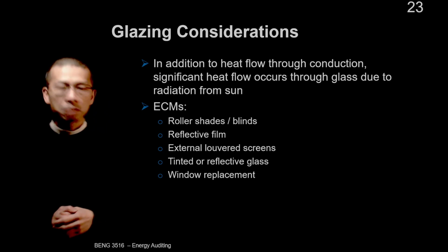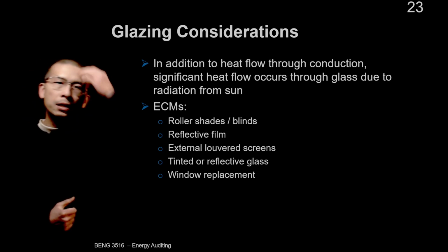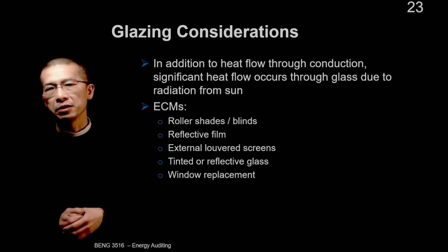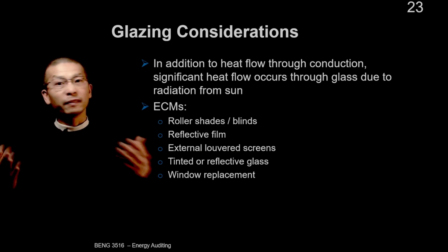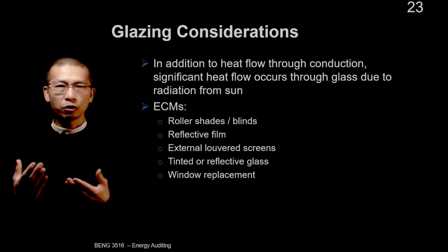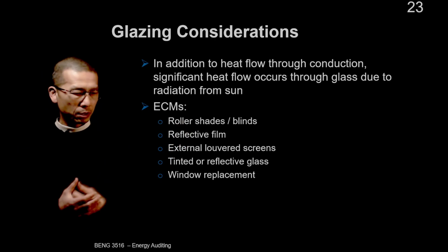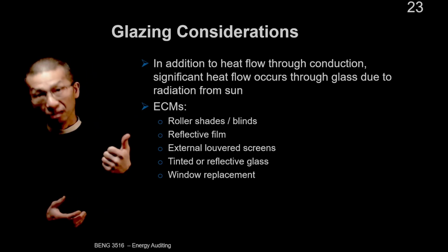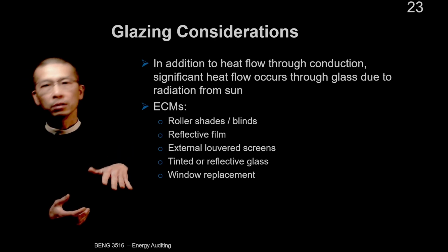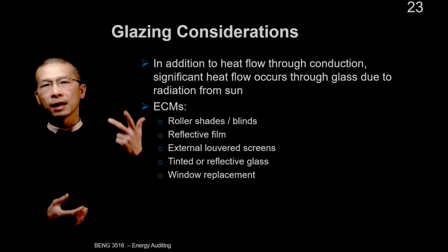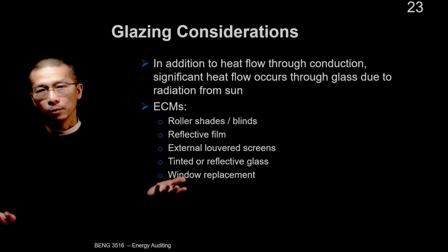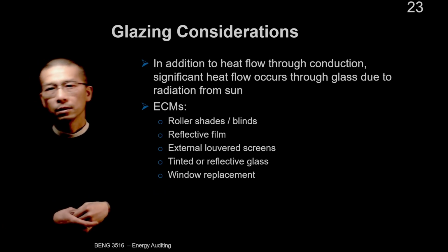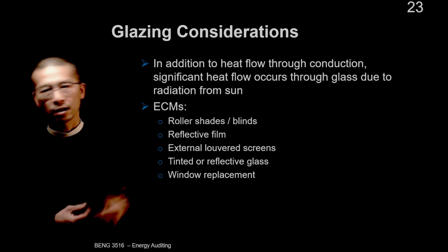For windows, we have to remember they are the only part of the envelope that energy goes through in two ways, right? Two ways. Thermal means low temperature conduction, convection, and low temperature thermal radiation, basically. So that's U factors, R values, okay?